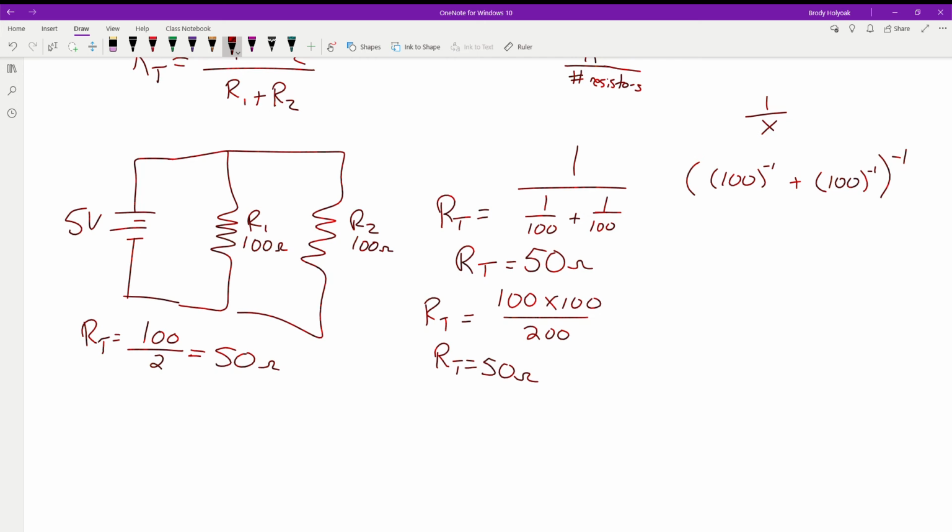So no matter what we did, do what? Depending on what you're trying to do. So the thing is, when you measure, we'll show this in lab tomorrow, but maybe I can do it here after a break, when you get your DMM, you can grab another DMM and measure when you're in the voltage mode. You can see how much resistance is in your meter. And your meter should be around 10 meg.